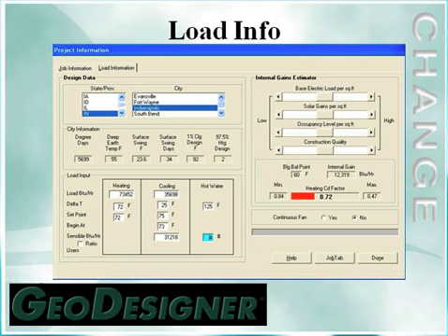We also need to know what our set point is on the thermostat for heating and cooling. And then in the cooling input, at what outdoor air temperature are we going to start the unit in the cooling mode? I'm one of those people that travel quite a bit, and with my house closed up and an auto changeover thermostat, I'll actually start running the unit when it's about 72 or 73 degrees outside. Realize this temperature is also the temperature that we're going to start an operating cost in the cooling mode.